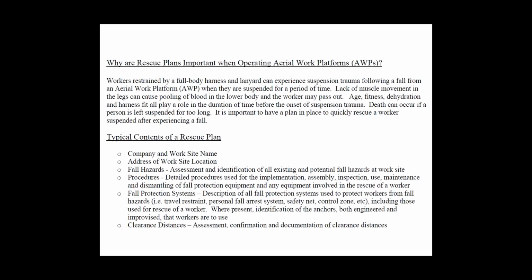So here's a typical content of a rescue plan. Again, company, site name, site specific, site location. So it's name, project, and site specific. Have the fall hazards been identified, all existing fall hazards on the work site? So what am I doing and what are the hazards that my employees are exposed to? Detailed procedures and implementations of these hazards. The assembly and inspection, use, and maintenance, for dismantling and putting together the fall protection. How does the guy put it on? How does he inspect it? And the clearance distance, based on the assessment of what type of fall protection you're using, the anchor point location. Have these clearance issues been discussed?